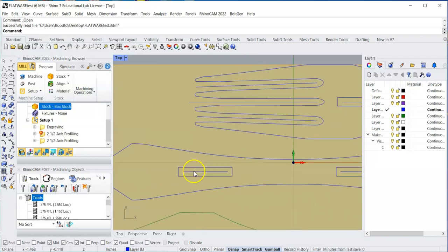Okay? So what I did was I drew a line from midpoint to midpoint, and then I measured that line, and I subtracted 1/8 inch, because I would be subtracting off a 16th inch off of one end and a 16th inch off the other end of that line. And I scaled that line 1/8 of an inch shorter. I'm confusing you, aren't I? Okay. So I did this, it'll make sense in a second.